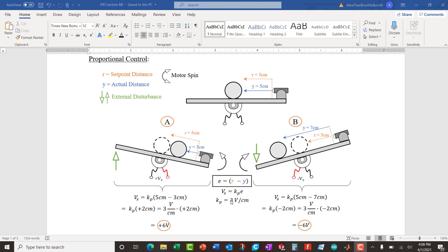If you don't know how to filter your sensor well, keep in mind the closed loop feedback system takes the sensor signal and feeds it back to the actuator. So if you have a very noisy signal, the actuator is going to be noisy also, and this beam is going to be back and forth, very noisy, right? And that's pretty terrible because the noise is going to be amplified in the system, and that's a problem with D control. Not a lot of people know how to filter properly.